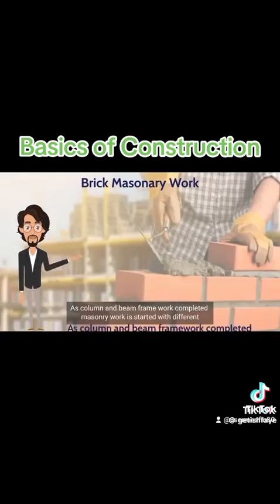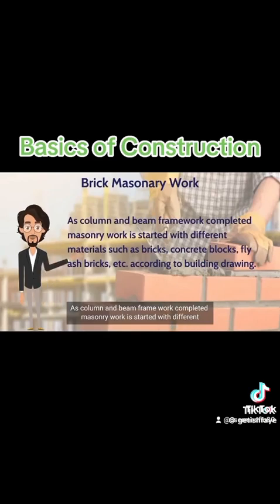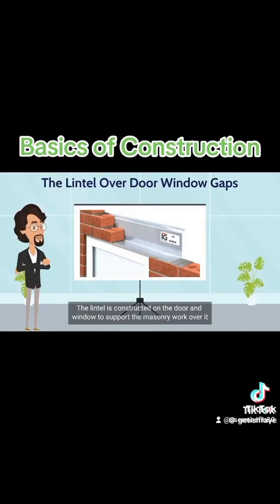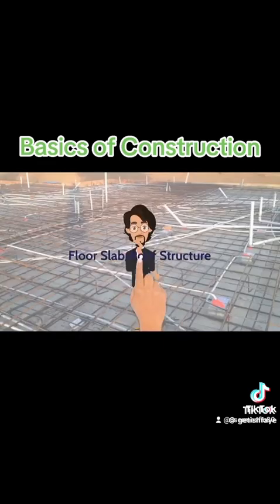As the column and beam framework is completed, masonry work is started with different materials, such as bricks, concrete blocks and fly ash bricks according to the building drawing. Masonry work is done using a cement mortar mix, a mixture of cement and sand. As per drawing, gaps are left for doors and windows during the masonry work. The lintel is constructed over the door and window to support the masonry work over it. After this, further masonry work is done.